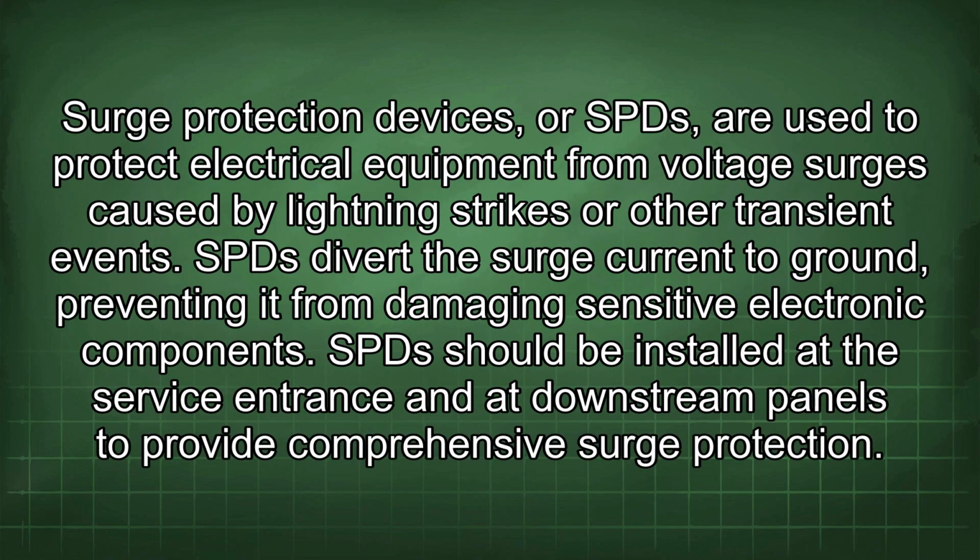Surge protection devices, or SPDs, are used to protect electrical equipment from voltage surges caused by lightning strikes or other transient events. SPDs divert the surge current to ground, preventing it from damaging sensitive electronic components. SPDs should be installed at the service entrance and at downstream panels to provide comprehensive surge protection.